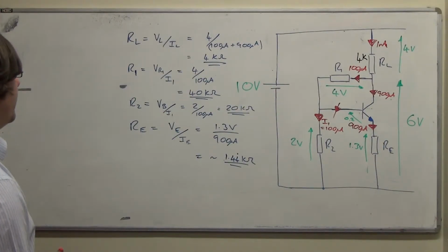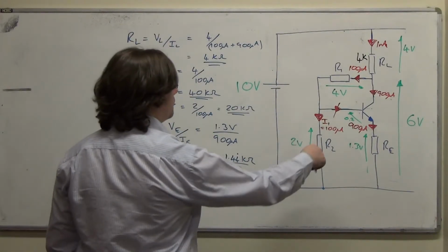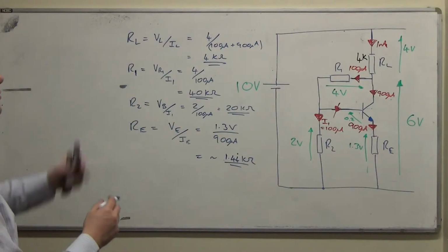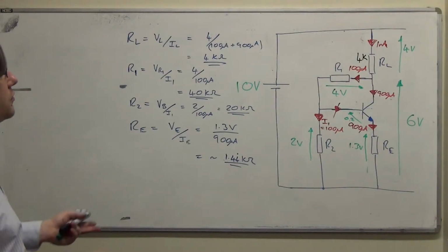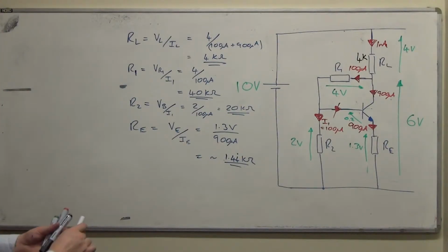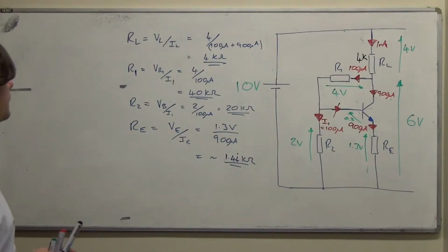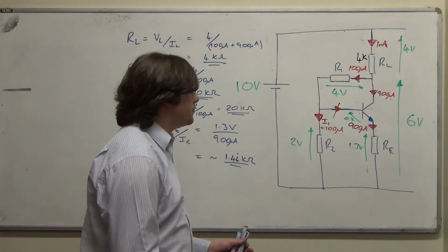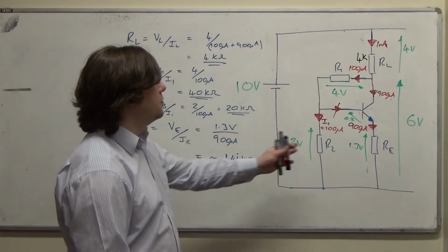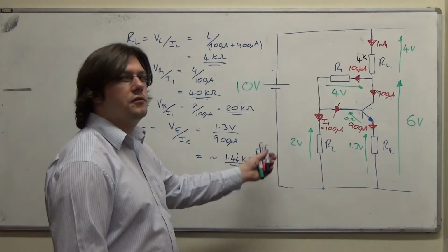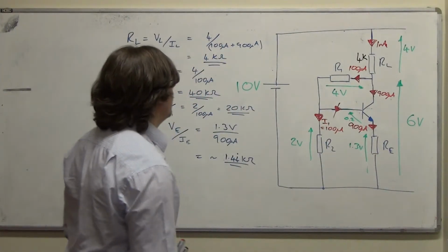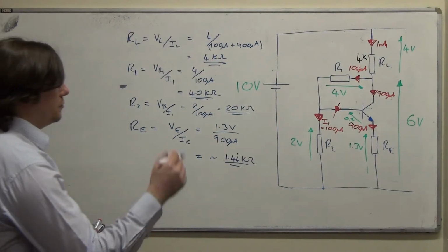Alrighty, so that will be self-consistent because we chose our voltages and then we chose our currents and then we worked out our resistors accordingly. So that Ohm's law will apply to the resistors, and that will produce the answers we're after. If I decided I was feeling mean, I might pick some of the resistors and leave others, or pick some of the voltages and leave others. I might choose I1 and not choose IC or something like that. In which case you can't just apply the method blindly.